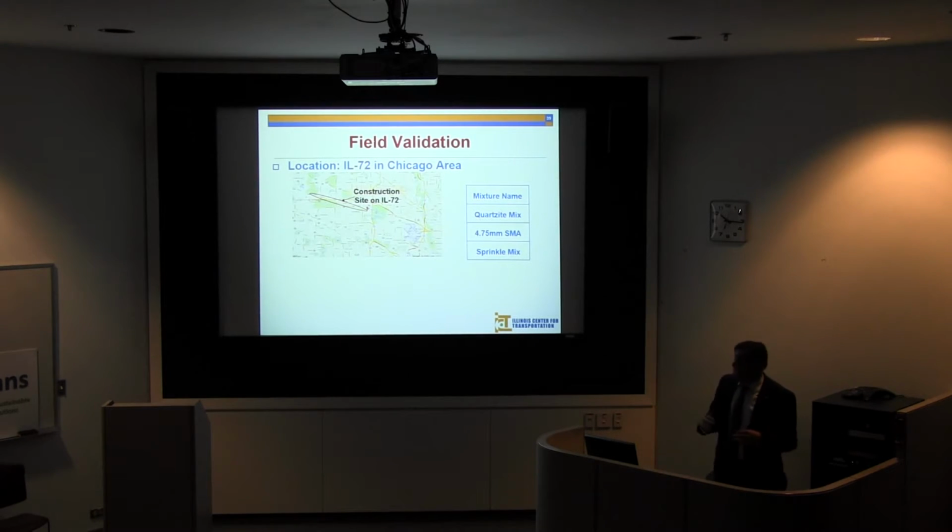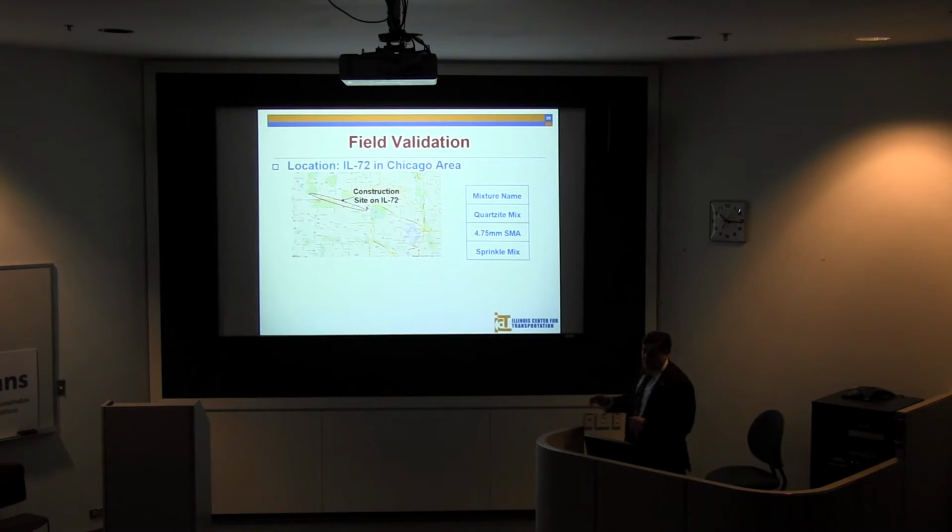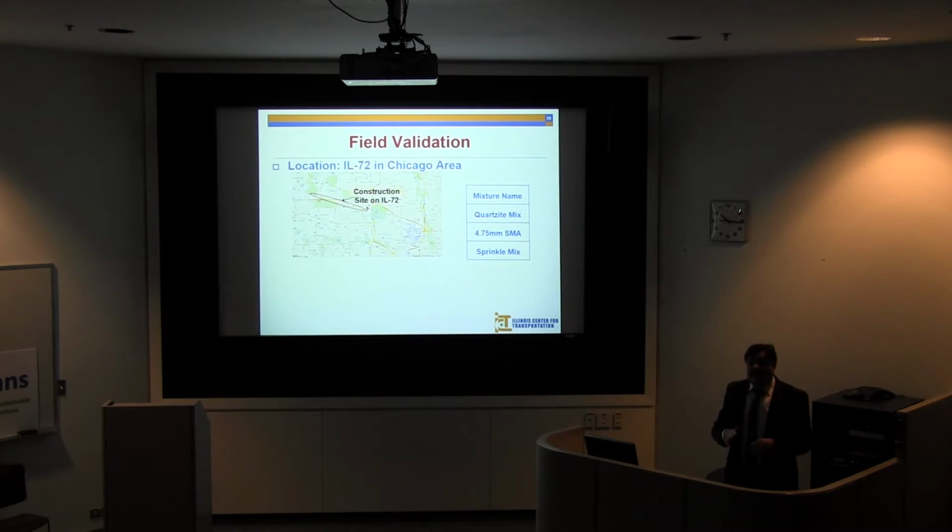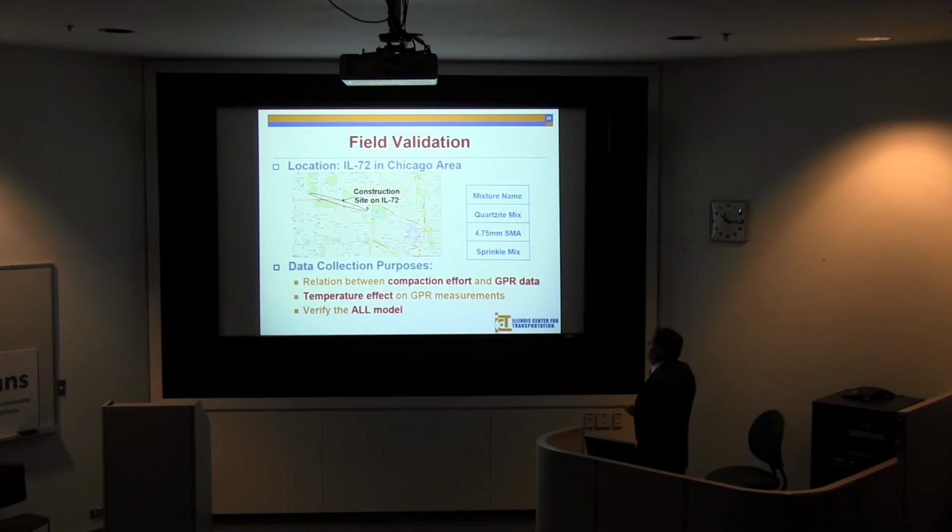So the sprinkle mix is simply to use the limestone and then get some of these quartzite and coat it with asphalt and just spread it on the surface during the compaction. And that will give you very good friction, safety, and at the same time, I guess we had really very good success. Let's put it like this. So we included this in what we are looking at.